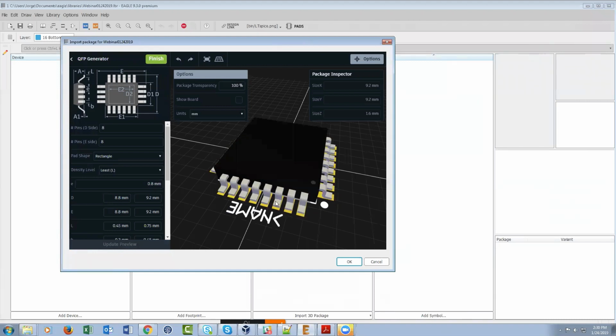They're really tight around the pins. Placement's going to have to be perfect. But on a really dense layout, you may need that. Okay, so that's least. Obviously, most is the opposite of that. Maybe you're going to solder by hand. You want to try to make your life as easy as possible. You may pick most. And again, look at the pads. Keep an eye on what's going to happen when I update this. You'll see they get longer. They get even a little bit wider.